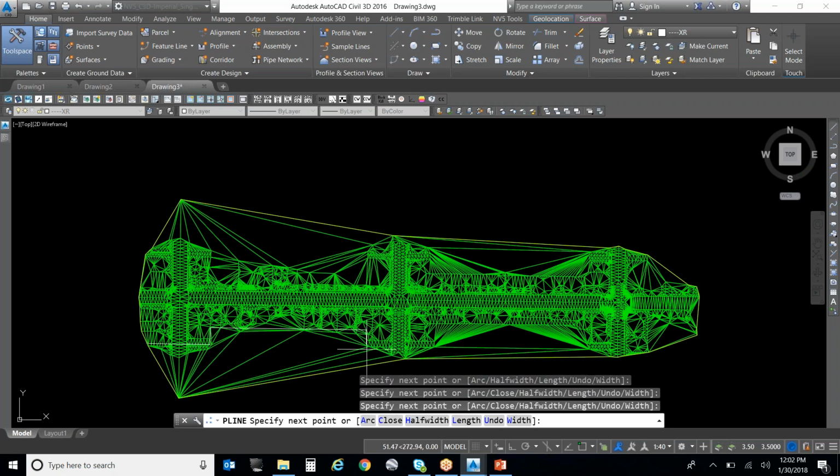Right. When Civil 3D first came out, whoever used Civil 3D 2009, anytime you did a 3D orbit, the program would crash. Crash hard. 13 got way better, right? 16's even better, but 18's even better. Please save before you do a 3D orbit. Just trust me, I've experienced a lot of pain with that. Unfortunately, Civil 3D is a 3D modeling software, but doing 3D orbits is not its strength. Just be aware.